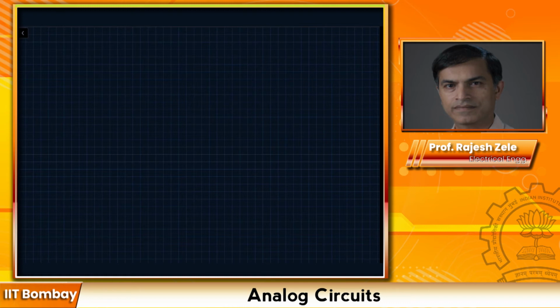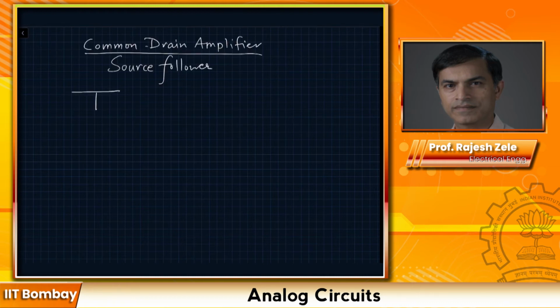After the emitter follower, we will start looking at its MOSFET counterpart, which is the common drain amplifier, also called the source follower. So please draw the schematic. In this case, transistor M1 is assumed to be in saturation, so a proper bias voltage VB is applied at the gate of the transistor. So you can do small signal analysis, in which you will see,